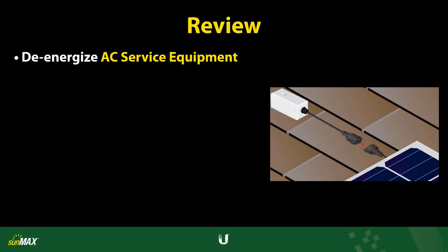To review, before working on the end run, the AC service equipment should be completely de-energized for safe work conditions. It is highly recommended that you work with a licensed electrician to ensure that local requirements are met relating to the end run wiring, conduit path, and general electrical work.